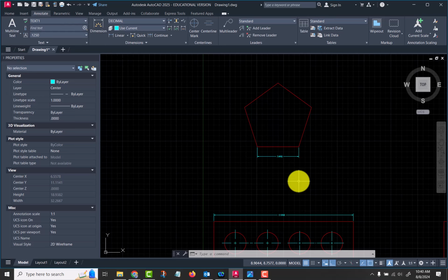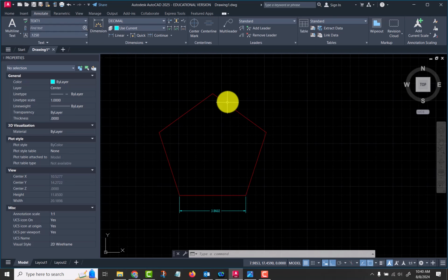The scale command, now I know we did talk about that, but sometimes, especially when you're drawing these weird shapes like a pentagon, yeah, you could draw it with the length option for the side, but the pentagon is one of those shapes to where the radius of the circle that it's inscribed or circumscribed about doesn't mathematically play well with the size of the shape, okay, because it's a weird angle for all the angles.